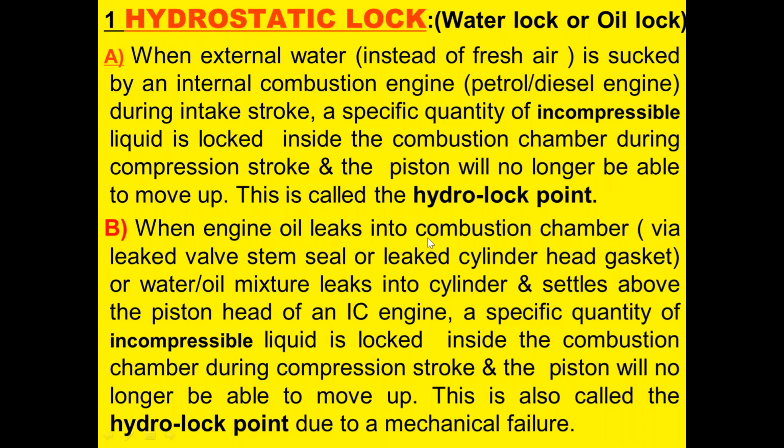When engine oil leaks into the combustion chamber via a leaked valve stem seal or blown cylinder head gasket, or a water oil mixture is taken into the cylinder and settles above the piston head of an IC engine, a specific quantity of incompressible liquid is locked inside the combustion chamber during the compression stroke, and the piston will no longer be able to move up.